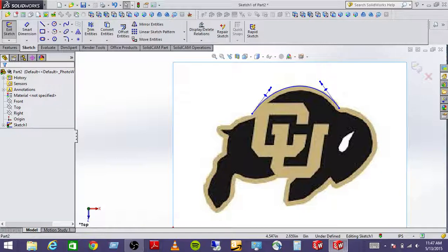So you just change the path that it's run. It's the same path it's going to run. It's just you're either rerunning it a second time so the laser hits it again, or you're adjusting the power settings on the laser for, let's say, the horn. Let's say you slow the laser down by 10%, or 15%, and that will give more exposure time with the laser to the plastic, and then maybe you up the power by 10% as well. So the laser is more powerful and it's going slower. You should get a deeper cut. Or you can run over it multiple times.